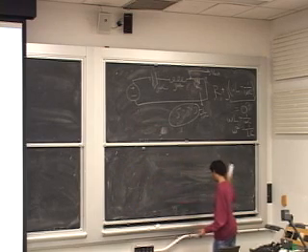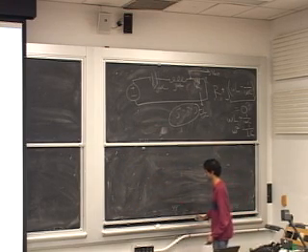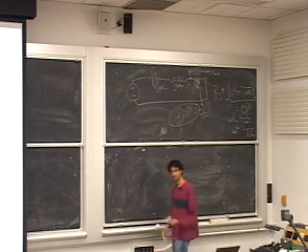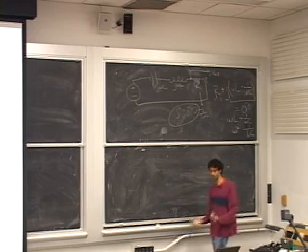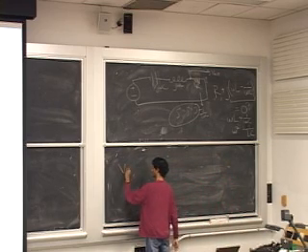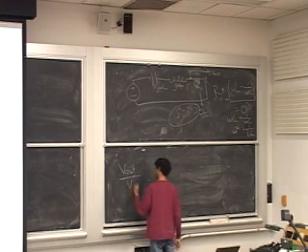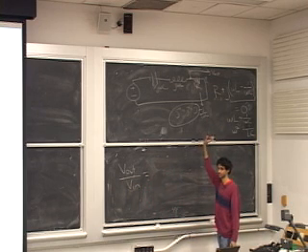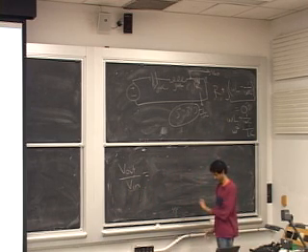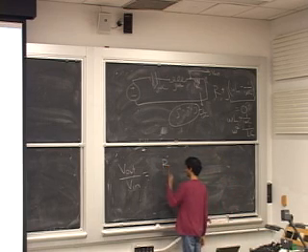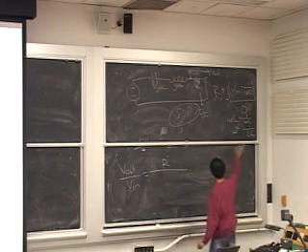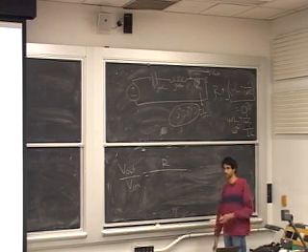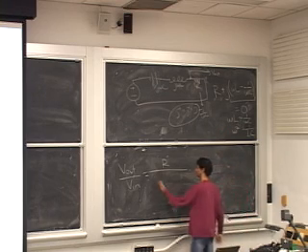So now let us look at what is going to be the output voltage, V out. How can we express this relation? So again, this is a series circuit, so we just need to do a voltage divider. So V out over V in equals, and again, I changed this up a little bit. I'm sorry. It'll make more sense based on what I started talking about. We have a resistor R on the top, and now we have our total impedance on the bottom. Does that make sense to everyone about how I constructed the voltage divider?